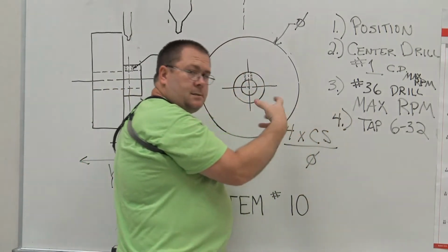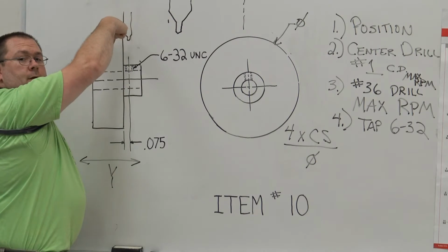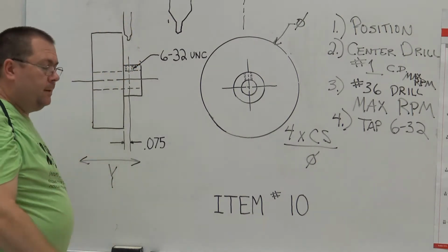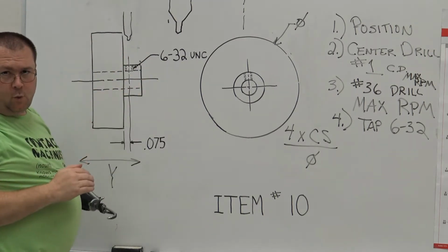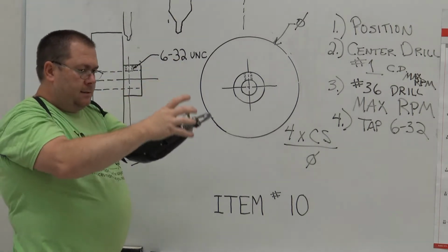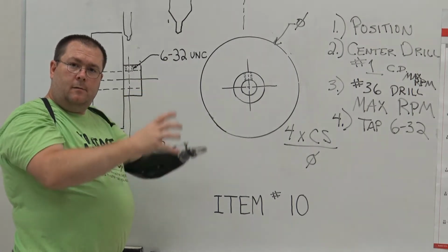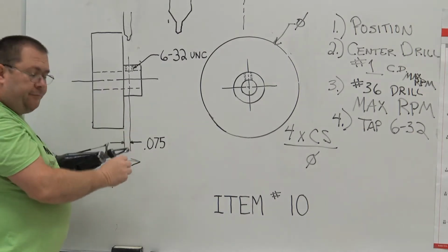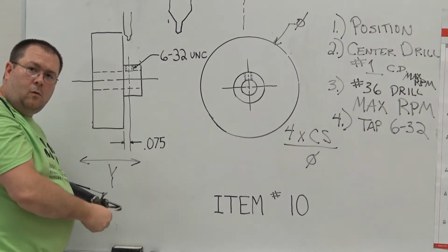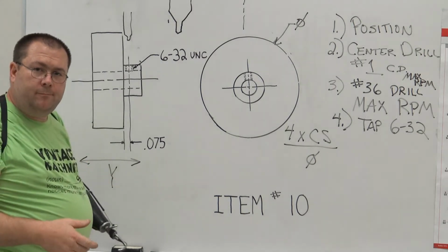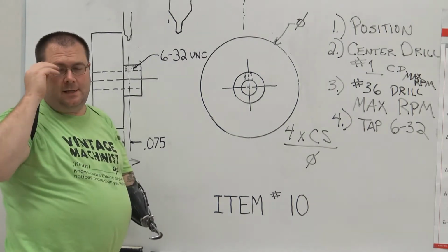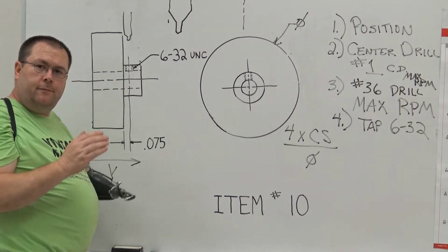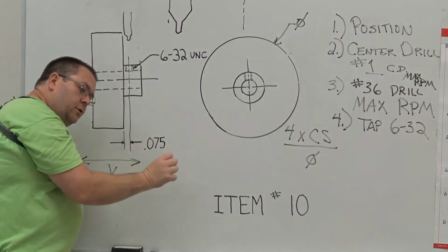And we're going to twist. Once that tap gets positioned right over the hole, we're going to rotate the spindle, which rotates the tap, and hold pressure down on the quill. The quill is the body that telescopes in and out of the head, right? And as we rotate with quill pressure, it's going to feed down inside that hole. Now once it takes grip, and when I say takes grip, it needs to take grip 2 or 3 threads. Now we can take our hand off of the quill handle and turn the spindle.